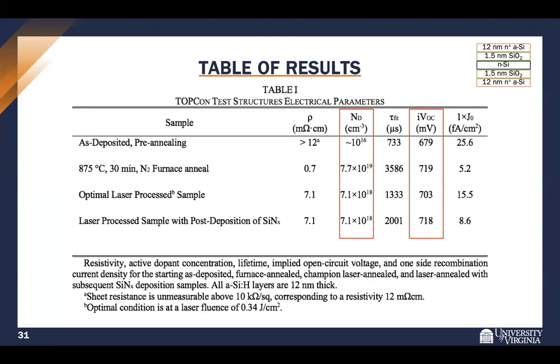Right. It also has a field effect passivation, I believe silicon nitride does, and this can further improve band bending within the full thing. So it provides some sort of charged layer which repels the carriers. Yeah, so that also helps there. I just did this at the end. I didn't characterize what exactly is happening with that one, but I can look into that some more. Slide 31, what exactly the silicon nitride does to the passivation. Okay. But this work definitely shows promise of laser processing. Yeah. And then cool, thank you.